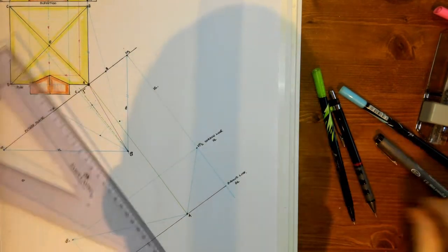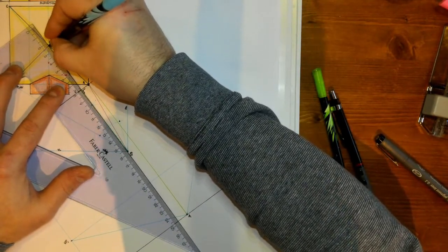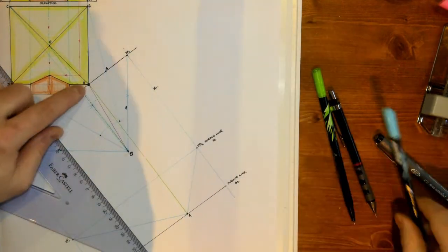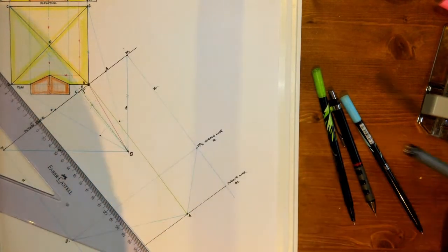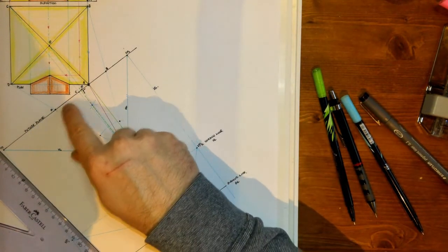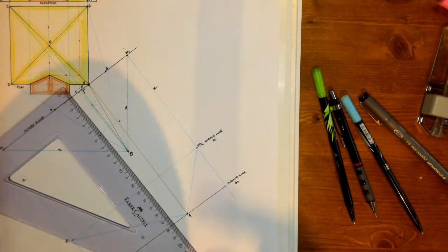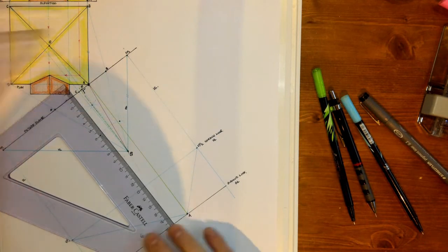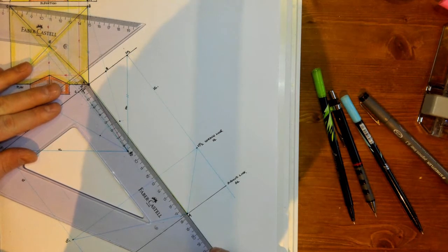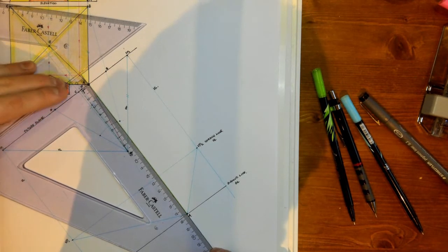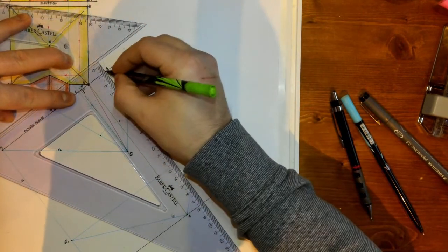And then point O. Where point O crosses the picture plane, we'll bring point O back to S, and we'll get the point right here. So that's O. Now, I have those points there, D, C, O and B, brought back to point S. That's them on the picture plane. So, now, let's just bring them down. Okay, don't worry about anything else. Let's just go to our line there for A, that one there, and we'll line up our set square there, and we'll do our sliding set squares to bring those points down. And I'm just going to bring them all the way down to hit the ground line.